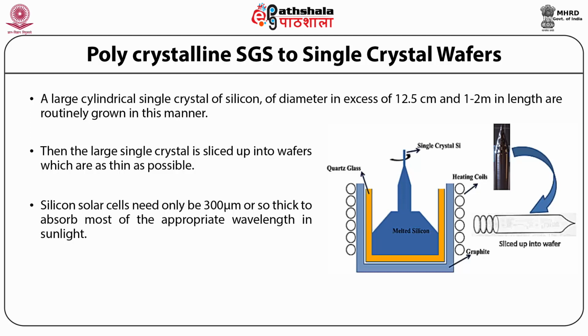However, the cutting of the wafer is quite difficult, which results in the wastage of silicon crystals. Generally, saw blades used to cut the silicon crystal have same thickness to that of the wafers, and therefore 40 to 50% of the material gets wasted in this process. Moreover, the wafers got damaged while slicing, which needs to be cleaned by acid etching.